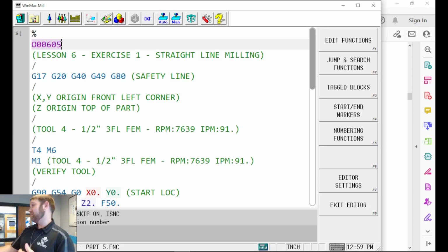Now, if I go back into that same shop a year from now on the same exact day, I'm going to look in their programs, and if I've already got 1, 2, 3, and 4 in there, I'll just pick up 2095. Does that make sense? That's how I number programs out in shops, unless they say use the serial number. If they don't have a standard way of doing it, I just implement my way. So just keep that in mind.